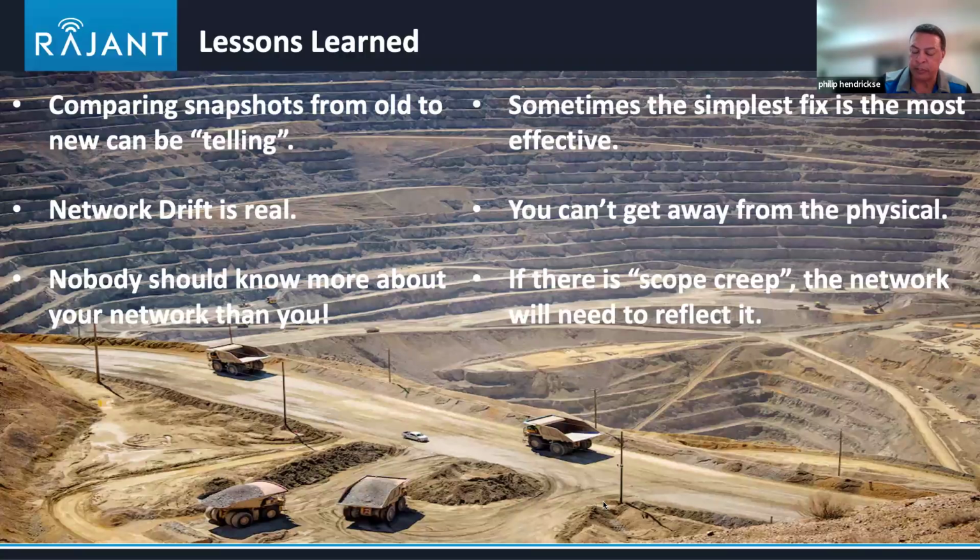And also remember, on some machines, like Caterpillar machines, the presence of a GPS puck, a little magnetic GPS puck, is not always feasible, especially on the great big 797s. You can actually get GPS information directly from the Caterpillar GPS, whether it's an MS352 or the latest one that they have. You can generate a GPS server on that and push out an NMEA string and get the breadcrumb to talk to that NMEA string over IP.